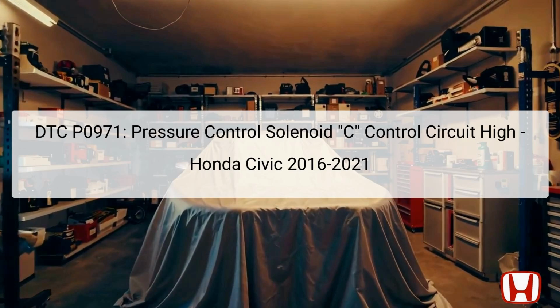The DTC P0971 indicates a problem with the Pressure Control Solenoid C control circuit in the Honda Civic models from 2016 to 2021. This solenoid plays a crucial role in managing the hydraulic pressure within the continuously variable transmission, CVT. Specifically, it controls the hydraulic pressure for the forward clutch and reverse brake, which are essential for the proper functioning of the CVT. When an error occurs, the Transmission Control Module, TCM, registers this anomaly and stores the diagnostic trouble code.